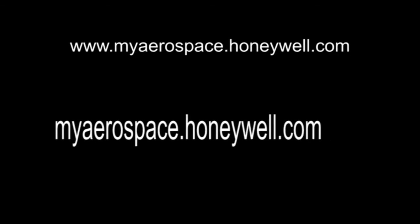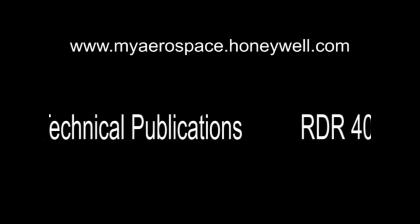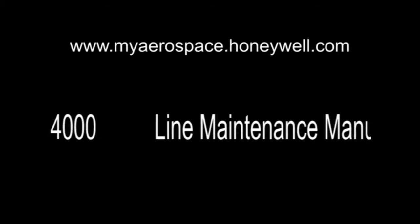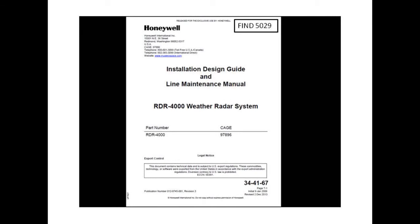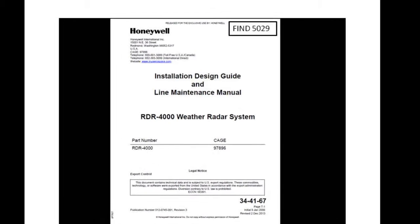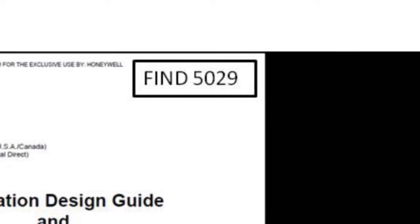Now that you know what fault codes have been stored in the radar processor, we can go to the Line Maintenance Manual, or LMM, to see what the best methods for troubleshooting are. From the LMM, type Control F on your keyboard to open the Find function in the PDF. Type in your noted fault code in the window and strike the Enter key on your keyboard.